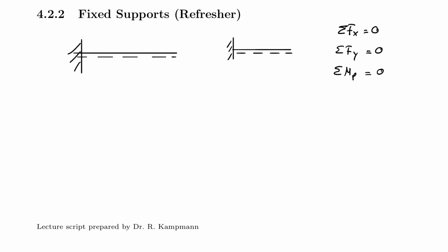Now, what that means in terms of a cantilever beam, and you can think of this as a balcony, right? The balcony that you probably have in your apartment complex or wherever you currently are. I'm sure you can find a balcony somewhere around you. You can see that there's only one support and not, as we had before, 2 types of support at A and B. So here we only have a support at A. And that support now needs to prevent these 3 things all in one.